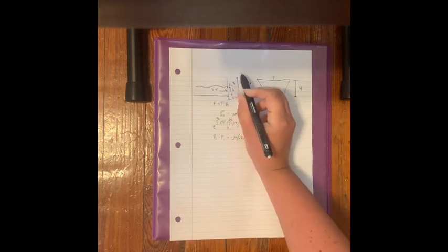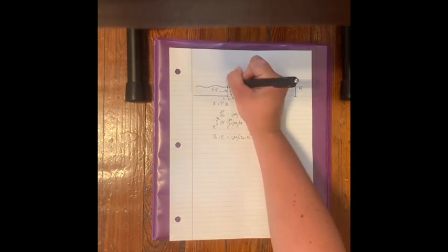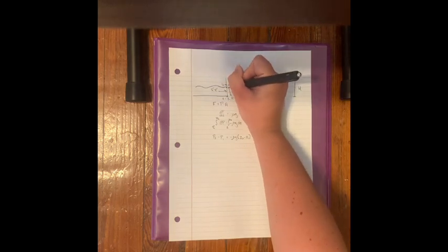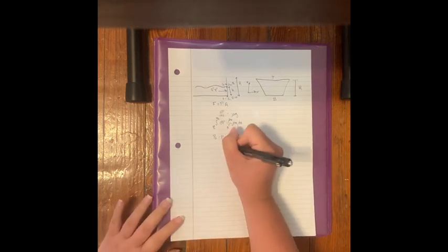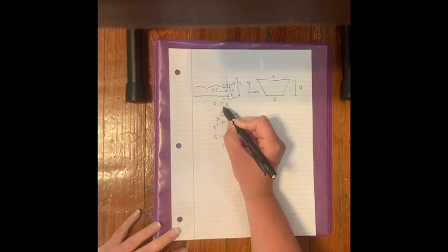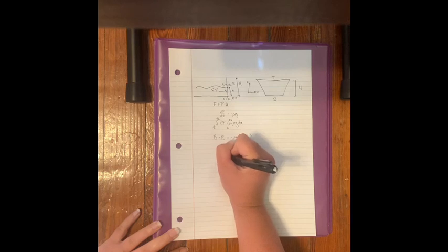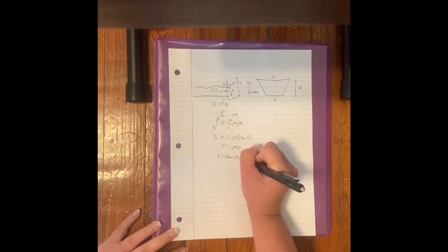Since we define this as our upwards direction, we're going to say that Z1 is equal to 0 and Z2 is equal to lowercase h, which is the height of our water. Plugging these in, we get that the pressure is going to be equal to negative rho gz. So now back to force is equal to pressure times area. We have the force is equal to, now our pressure is going to be P ATM minus rho g z times our area,